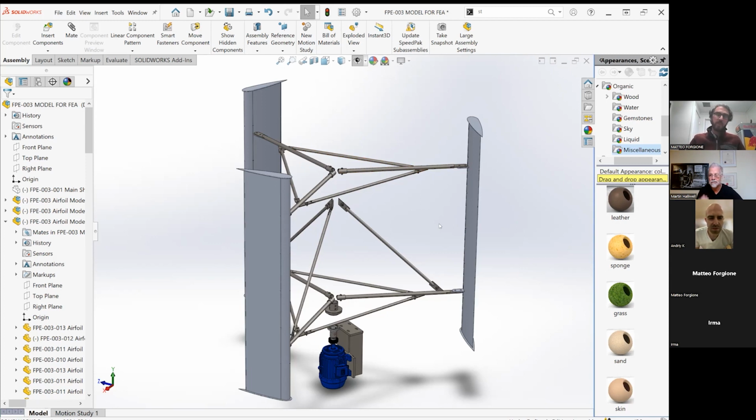You can say, okay, we know the approximate stiffness of the blade, for example. We know how long it is between these two nodes in the free length, and we can say, let's look at the first and second mode of vibration, and run a quick calculation based on some generic shape, and say, okay, the resonant frequency might be somewhere in this range. Now we have 3 blades, so we have a harmonic, so multiply everything times 3, and just start going through that process and look to see, is anything maybe going to be a problem here?